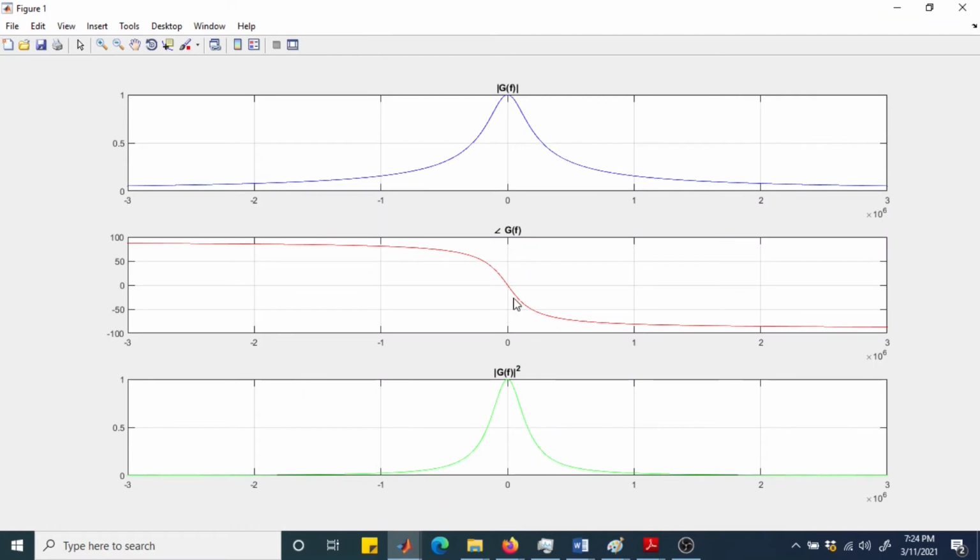You can observe from the magnitude response that the bandwidth starts from 0, and the gain is decaying, and it would reach 0 only when the frequency reaches infinity. So this is a decaying function, sort of an exponential decaying function. So the absolute bandwidth is from 0 to infinity, that is infinity.